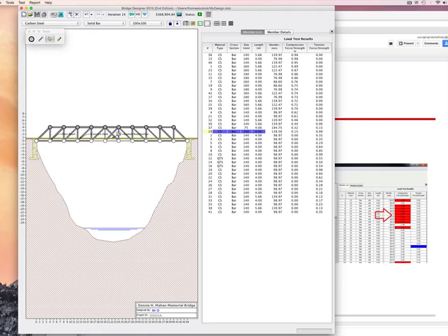All right, great. Now, one thing you do is watch here. If I click on compressive forces, this is going 0, 0, 0 on the compression forces, so that tells you they're all tension. The minute there's a value, you can see the tensions are now all zeros. So it can either be compression or it can be tension. It won't be both. And then you want to get it as close to 0.98 because that's as close to 1 without going over 1.